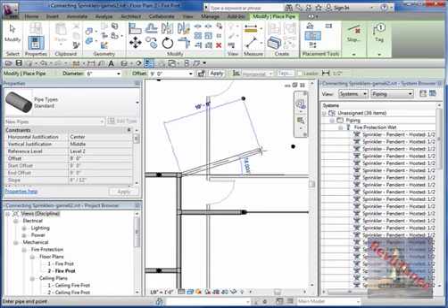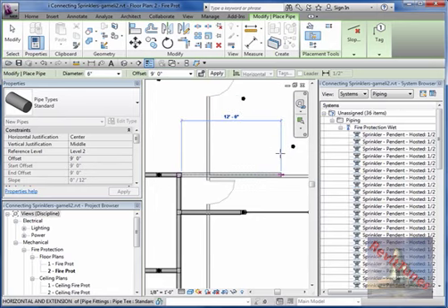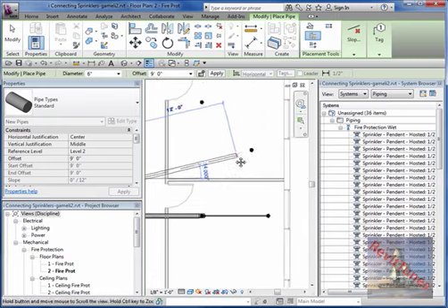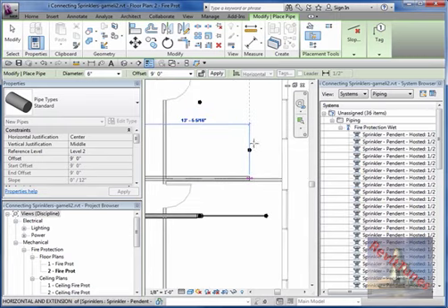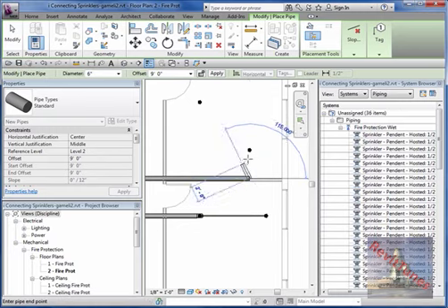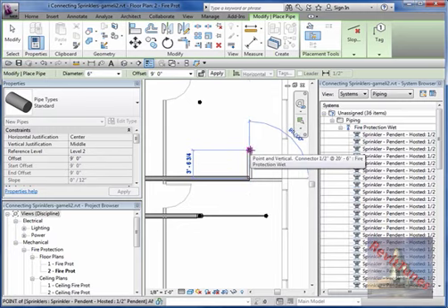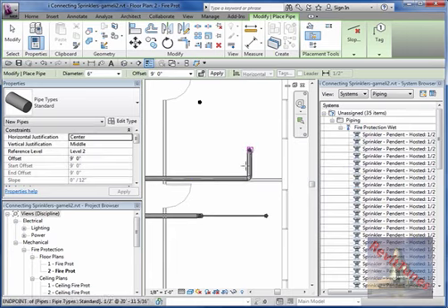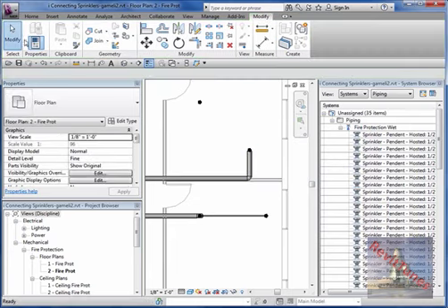So if I now hold shift and I keep moving, when these light up blue, hidden blue, that means I'm right there aligned to this other sprinkler. So I click, even though I'm outside, I'm not putting my mouse here, but because I have shift, I click, and then I let go of the shift, and then move it to the sprinkler, and it's going to grab the sprinkler. I click and I disconnect my command, and I take a look in 3D at what happened there.